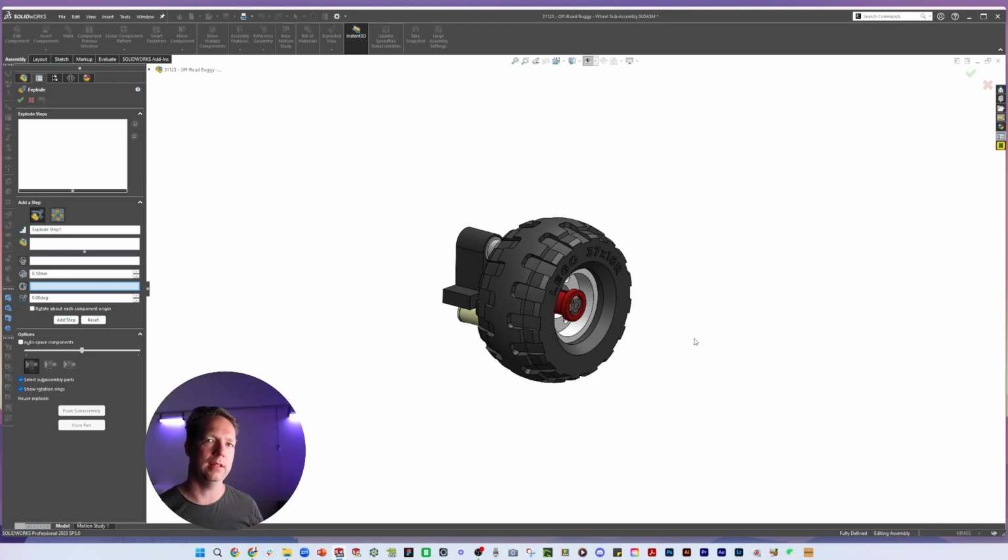So if you're communicating the exploded view in a two-dimensional drawing that's static, then it doesn't matter what order the parts are exploded, so long as they're spaced in the right position so that they're viewable. Okay. However, where the order matters is if you're going to do any animations. There are animation tools, very basic, within SolidWorks, but what they let you do is use, for instance, an exploded view that you've done, and it will move those parts out in the sequence that you've done in your exploded view tree here.